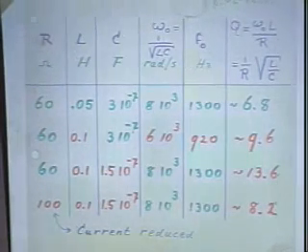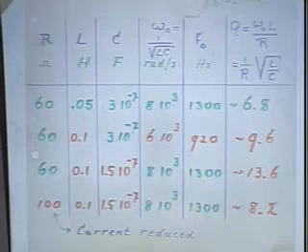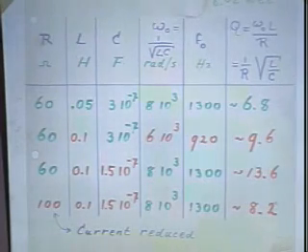The idea being that for these values that I have there, in the first line you see R is 60 ohms, and the self-inductance is 50 millihenry, and the capacitance is 0.3 microfarads. So that's a given there. And I give you here the resonance frequency, 8,000, in terms of omega, radians per second. This is the resonance frequency in hertz. And just in case you're interested, I give you the Q value there as well.